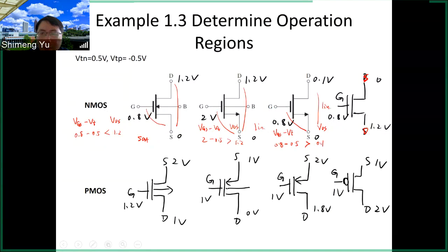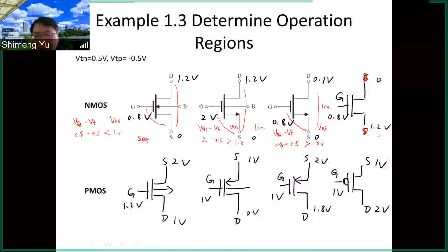What determines source and drain depends on the voltage bias you apply. For NMOS, the source is always lower potential and the drain is higher potential. So here you need to change the source and drain labels.